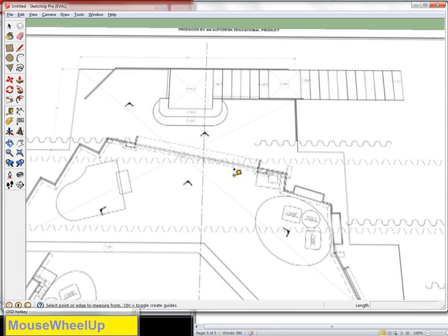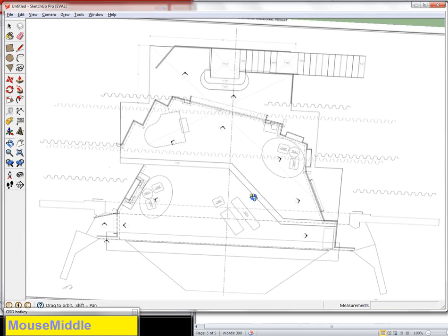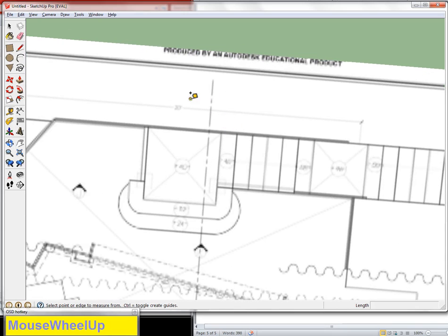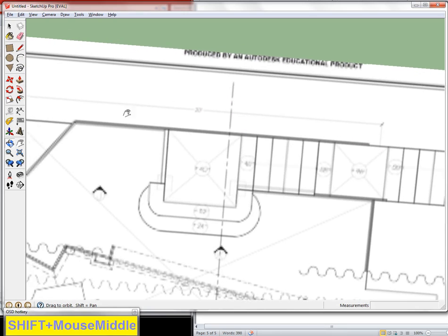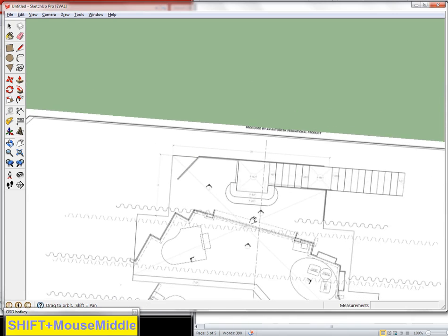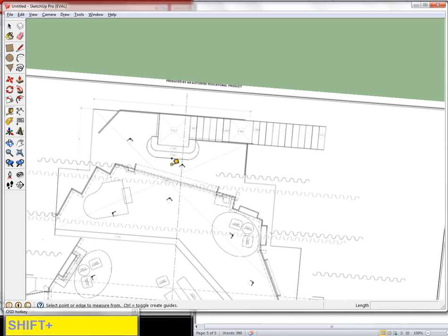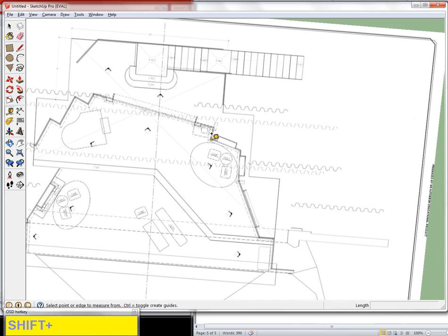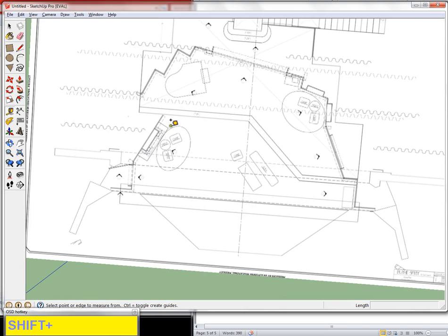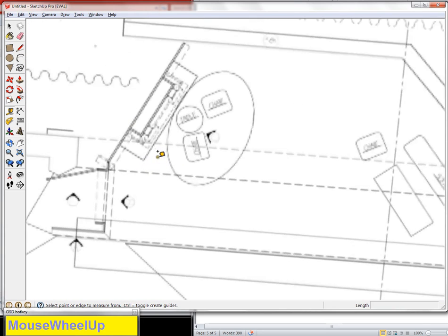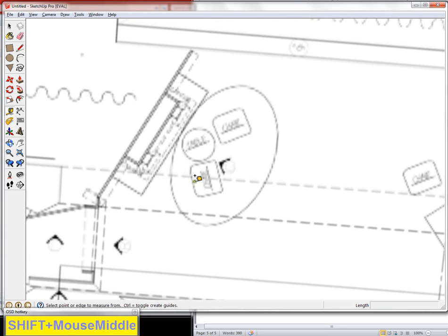Now there are a lot of items on this drafting, but if you zoom in, you can see that this says 20 feet from that point to that point, so we could use that. We could use something we know of, like we know that this is 4 feet. We know that this is 4 feet because we built this bookcase and we've built this staircase. We know that this is 5'8" because we've built this fireplace. And so what you do is you just come in and pretend like you're clicking on an item to measure it. So click on one corner and click on the other corner.